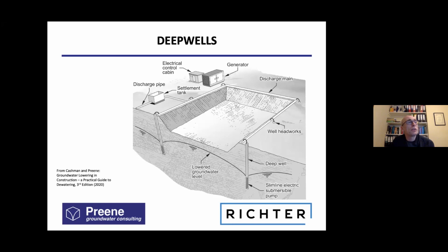I'm now going to move on to the deep well method. And the deep well method is quite easy to understand in that we install a well like you would have for a water supply well, for a house or for a community, and we install a slimline borehole submersible pump of the sort made by, for example, Grundfos.